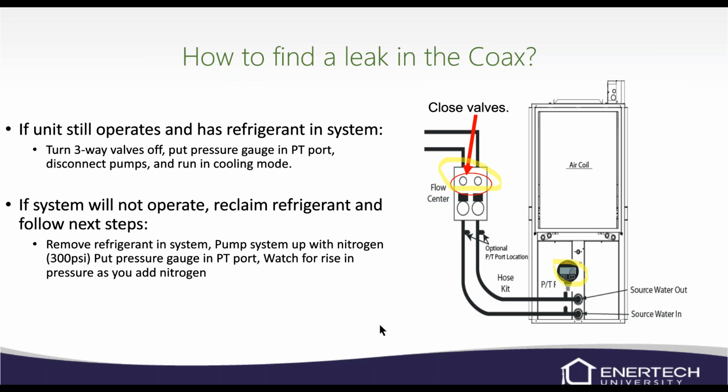Because for one, the heat exchangers are not easy to replace. So I wouldn't want to just go willy-nilly replacing a heat exchanger. I would want to find out for sure that that's what it is. If you have a braze plate and you think it got frozen or something, on a braze plate, normally you can tell because it'll be swollen in a certain area, and then you know it's breached. On a braze plate, it usually shows pretty quickly too. It'll usually dump pretty quickly.